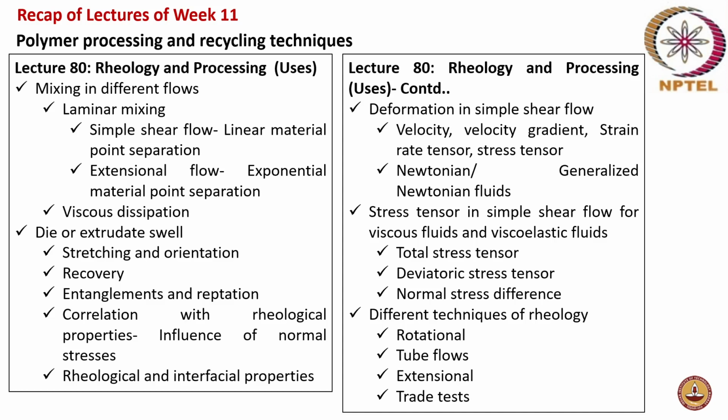What happens because of this? So the material coming out will not have the same size or shape as that of your die, because of your stretching and orientation as it passes through the narrow opening, and then the recovery process once it comes out of the die.